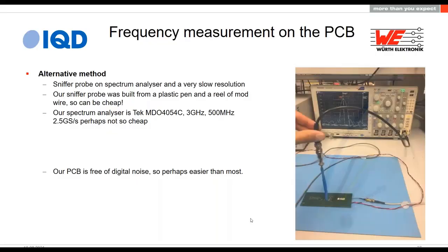And there it is, assembled, and there's my network analyzer, my spectrum analyzer with a peak on it, and here's my probe sitting on top of the crystal. Well, crucially, it's not actually right on top of the crystal because crystals have got a metal lid, and the metal lid is connected to ground, so that's an EMI shield, yeah? Where I put this is on the PCB track just between the crystal and the capacitor, and that was where I got the loudest signal on this probe, yeah?